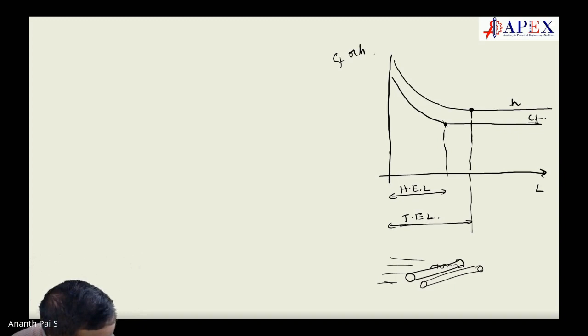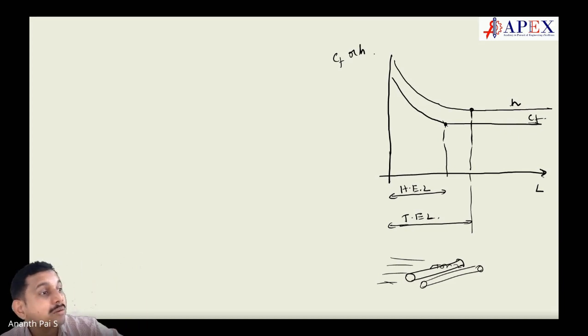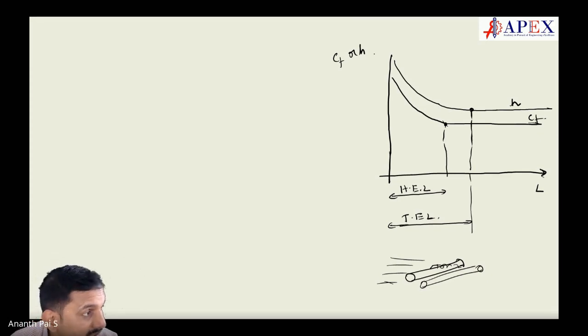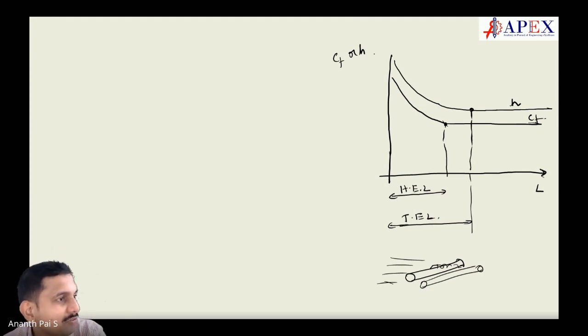You put more obstructions, more pressure drop. Heat transfer rate increases, of course. But then what heat transfer rate are you achieving? What are the economic benefits you are achieving because of the heat transfer increase? And how much loss are you going to have, or how much are you going to spend for that pressure drop? So there you have an optimum, and that optimization is done. Make sense? So engineering is all about optimization.